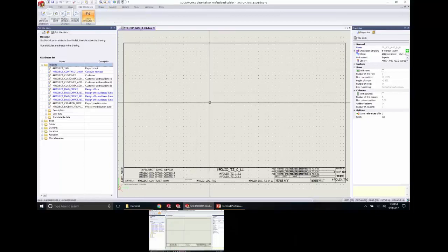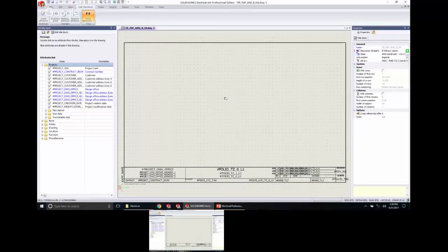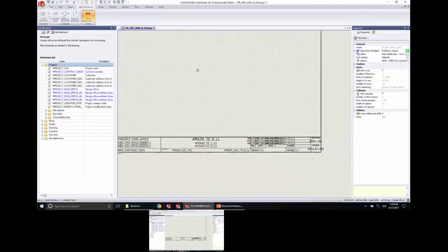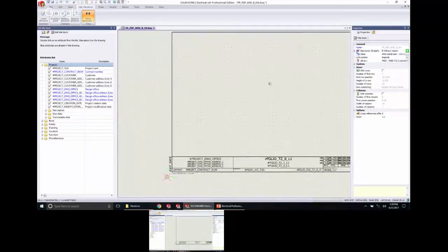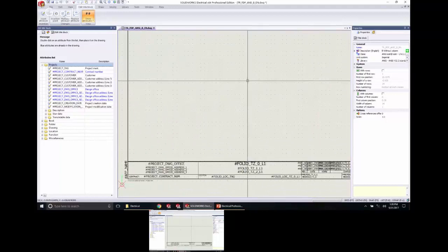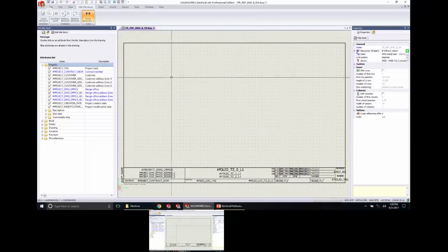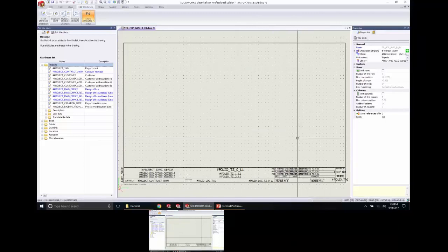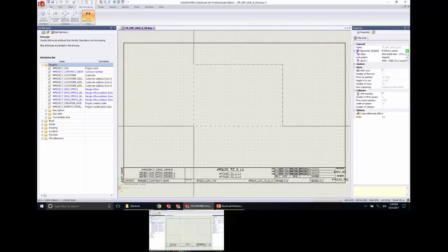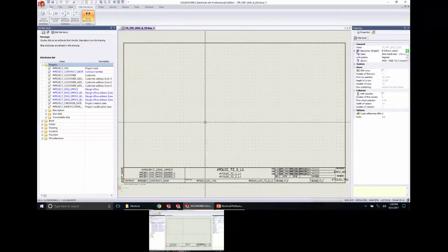Real-time pan: in this case, we're going to use that middle mouse button again. Hold your middle mouse button down. You see there's a hand there, so it's like you're grabbing the drawing and moving it around to wherever you want. You can zoom in and move that. You can also do window selection: left to right to select everything inside a window, right to left to select everything crossing a window. So it's typical like that.